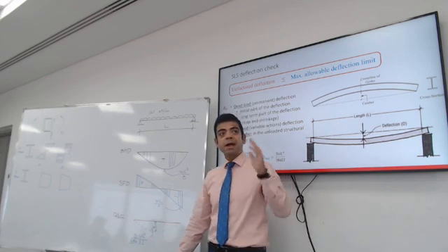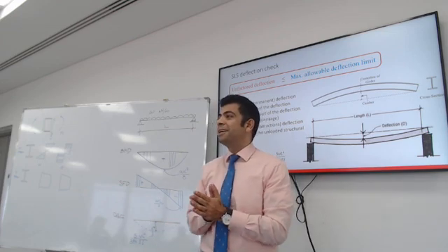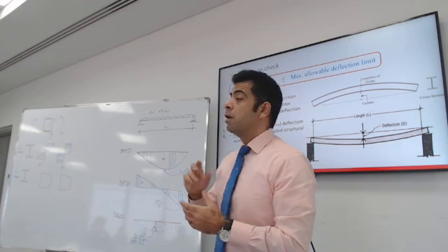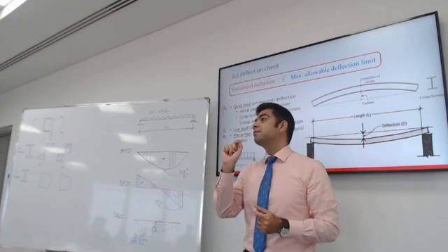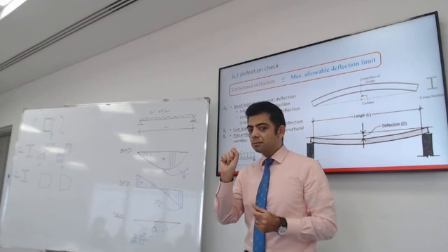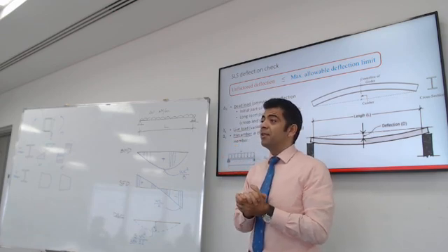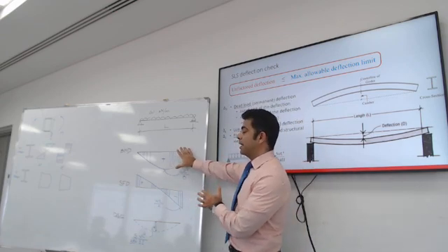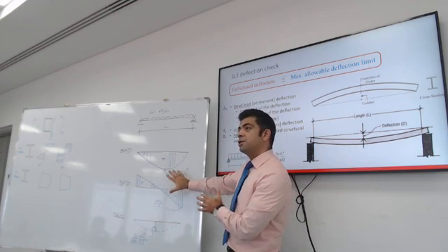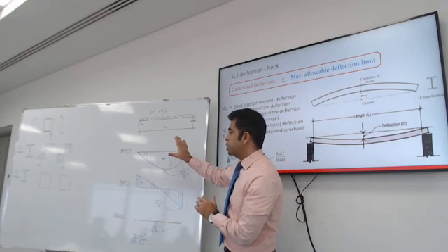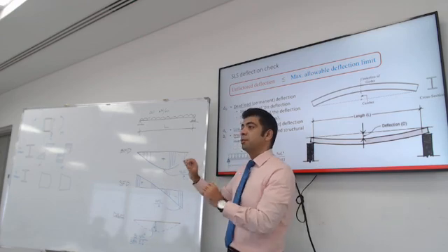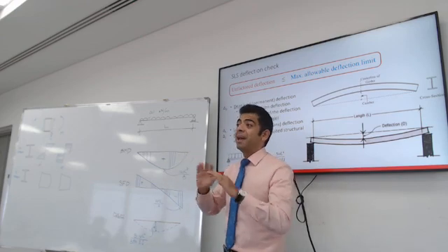And as a matter of fact, let's just start with the deflection. So, checking deflection is under a different limit state than the safety or bending and shear. Bending and shear, this is ultimate limit state. You check these capacities to prevent collapse and catastrophic failure.